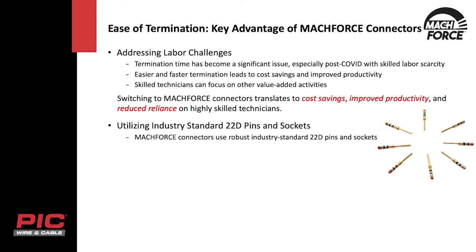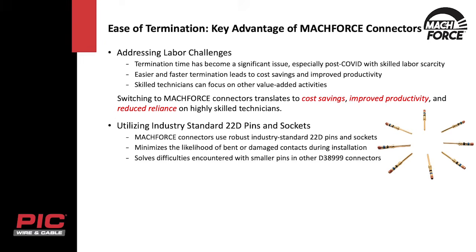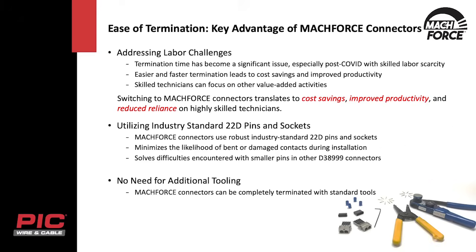Another important aspect is that MACHFORCE connectors use industry-standard 22D pins and sockets that are robust enough to minimize the likelihood of being bent or damaged during installation. This is key because the pins used in the contacts of other 38999 connectors are sometimes so small that even skilled technicians have difficulty working with them. A final note on installation is that MACHFORCE can be completely terminated with standard tools, so there's no need to procure additional tooling. To prove out the ease of termination, I'd like to walk through a quick video to demonstrate the process.